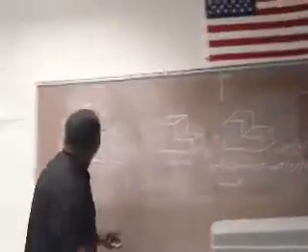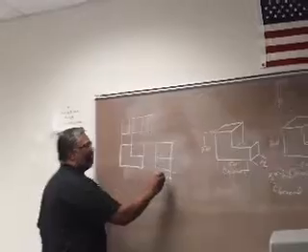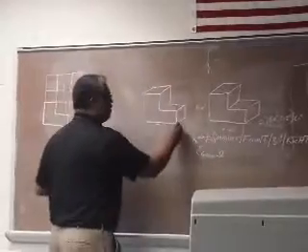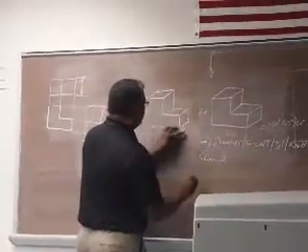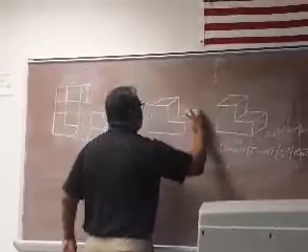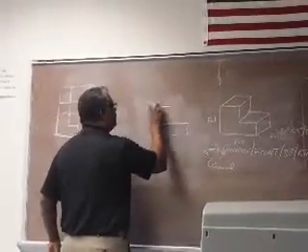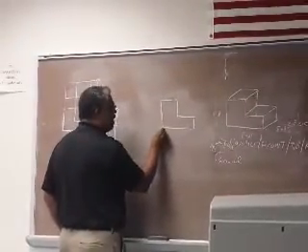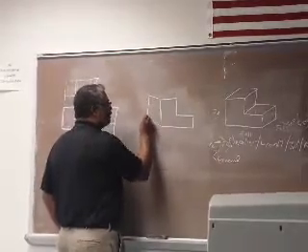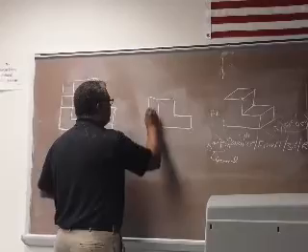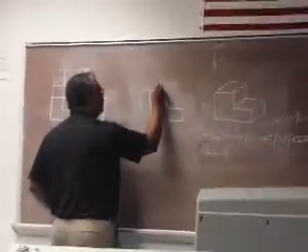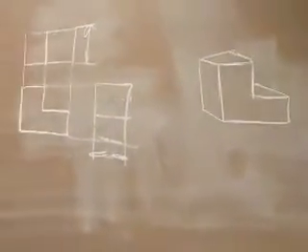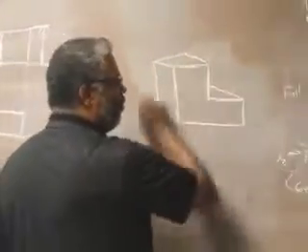Now, the point here is that I used the front view, and the logical direction to go is to the right. If I use the front view and draw this to the left, where my receding lines, the lines that show depth, go to the left, then depending on what happens there, I lose portions of this drawing.